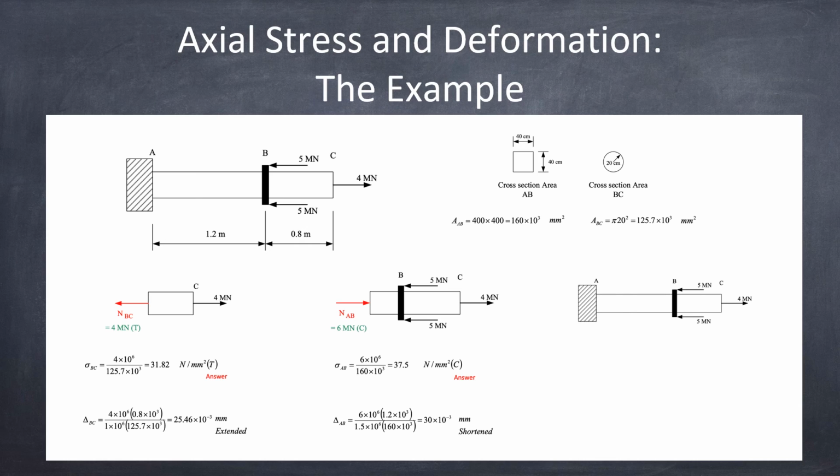Look at the geometry. Because point A is fixed by the fixed support, for A and B to become shorter, point B has to move toward point A, because point A cannot move. Therefore, the formulation is in relative terms: delta B equals delta A, which is of course 0, plus the change in length. And we can conclude that B moves to the left by the amount we calculated.